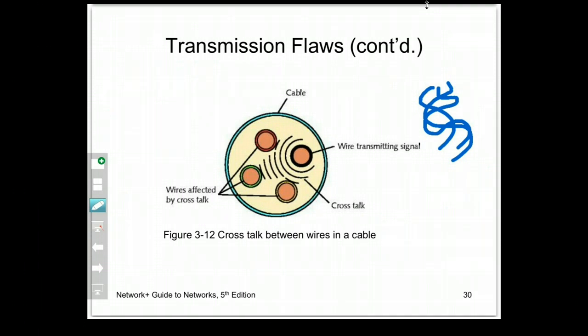You'll notice here where the gaps are is where the crosstalk happens. Okay, and I'll teach you that next week when we're doing our cabling. One of the things you want to watch for is when you're holding your wire, hold it pretty tight so that what's below doesn't untwist while you're putting together your cable and making sure all your wires match up.